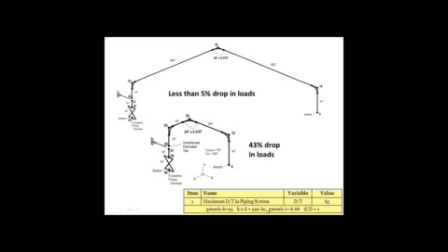You can see the KD ratio is a very big number. It's big with respect to all the lengths in the piping system. So for this small system, we dropped the pump loads by 43%. Now, as soon as we increase those run lengths, very, very little change. So if you're going to send us a model and you would like us to tell you how much it changes the loads or the stresses or the SIFs in your system, you would tend to send us this lower model and not send us that higher model.